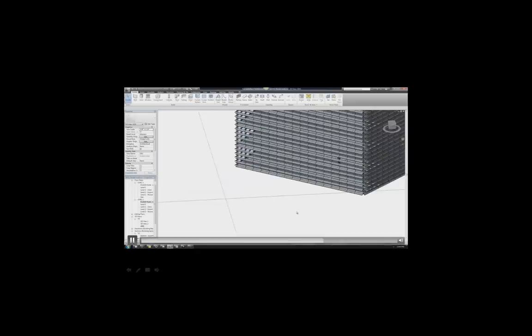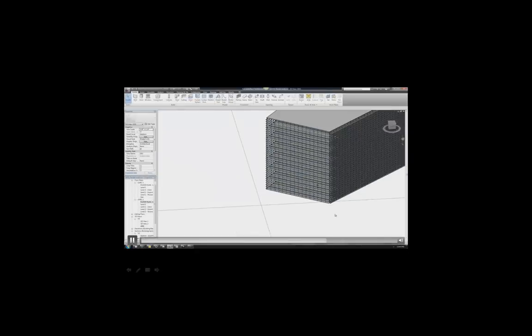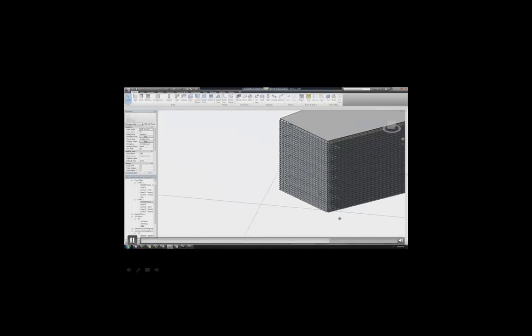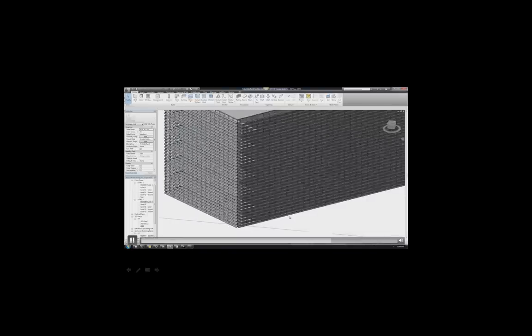So then we can go back into Revit, and we create these exterior shading families where we can adjust the parameters of the variables that we set, right? So we can select the actual shading family and go into its type properties. And here we can input that information.